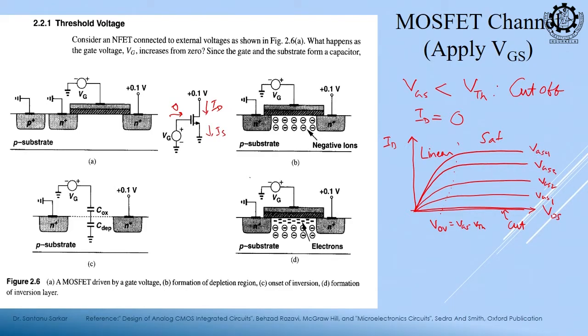Now, when you provide a voltage, remember this oxide. If you provide a positive voltage at the gate, what will happen? This charge will increase. So, the body will behave like the other plate, and in between we have the oxide, silicon dioxide, and the depletion region also. They will try to replicate the opposite charge. In other words, if I give a positive voltage at the gate, in a p type substrate what is the majority? Holes. Holes have positive charge, so holes will get repelled.